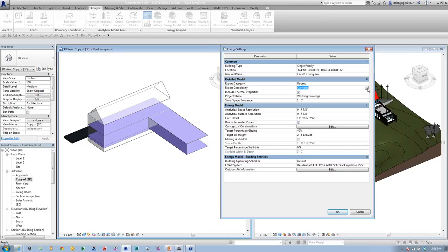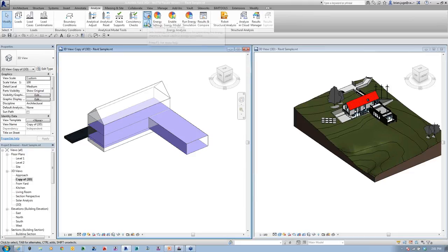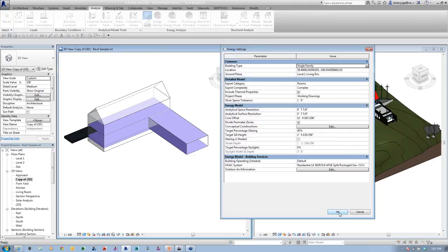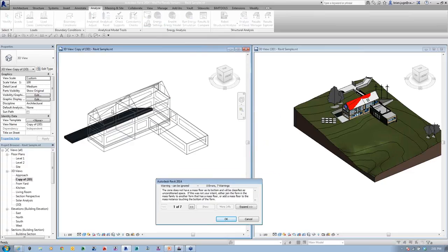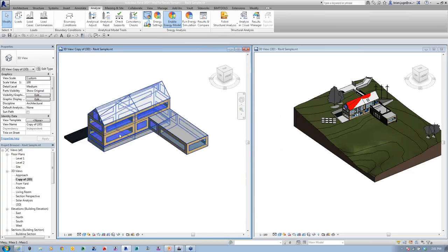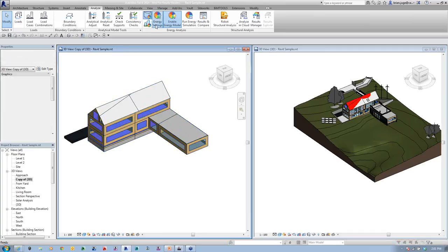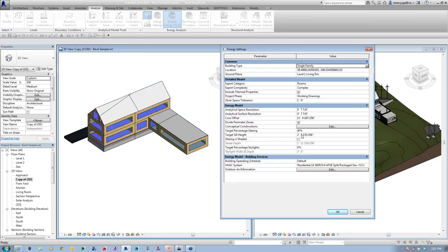And also, if you don't have rooms and spaces, if you're just doing a massing model, we don't necessarily need to worry about that yet. We can still perform the analysis by coming in here, looking at the energy settings, setting that up, and enabling the energy model, and then it'll actually divide that into its different zones for you. So in here, what it's done is it's calculated the glazing area, and I'll bring that back up in a second. It's taken that mass in here, and it said, okay, how much glazing do we have in here? Oh, I'm going to apply that to it.